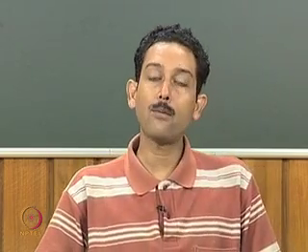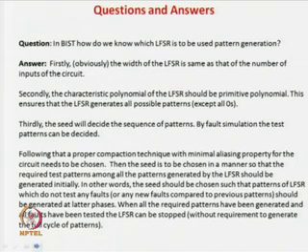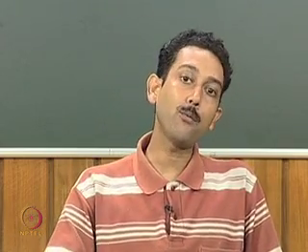Okay, so that was our discussion on BIST architectures. We have discussed two very important components of BIST. One is the random pattern generator, which uses an LFSR, and the other most important component of BIST is the response compaction and comparator. The comparator here is very simple, it is just a bitwise comparison, but the very important part is how you can compact your output response. Compaction should be such that your aliasing is minimized. In this case we have given examples that given the circuit, given the fault, given the input pattern, and the compaction nature, the aliasing values will change. So it is a design problem and you have to find out which one is the best for you.